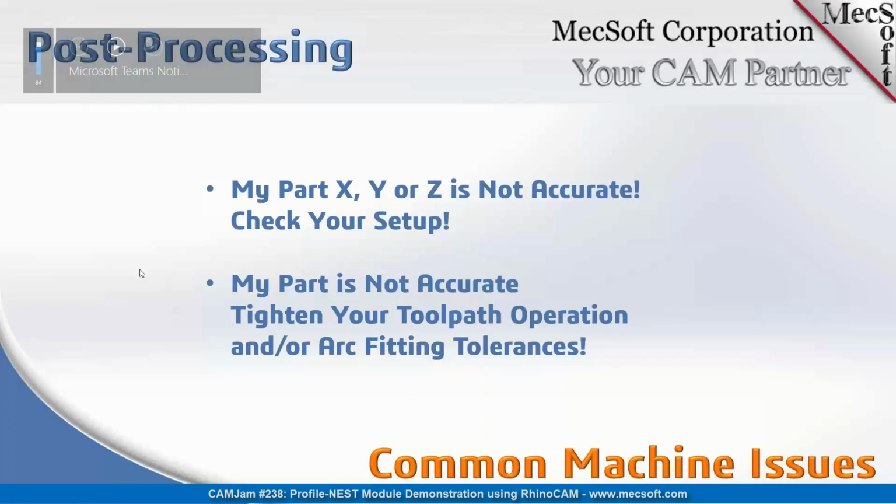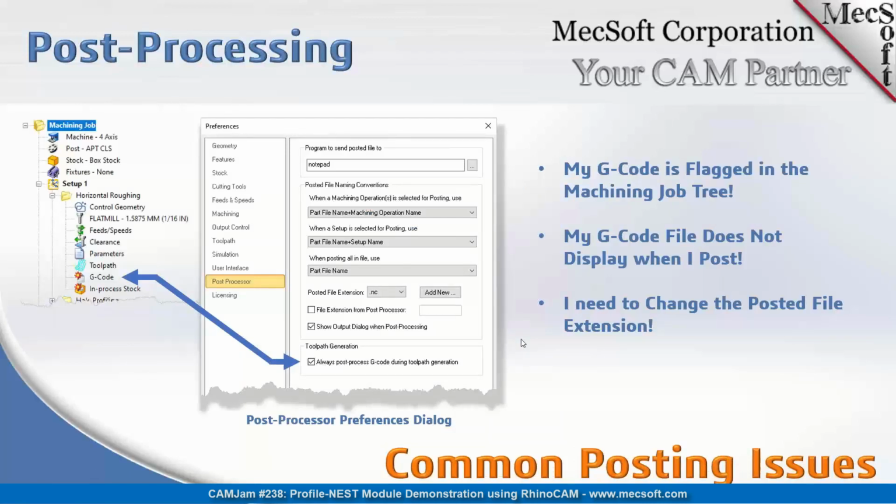Now here's a good question on upgrades, updates for service pack updates and things like that. Do your posts get overwritten? So yeah. Obviously if you edit any of the posts in our install path, do not save it as the same name, because those files are subject to be overwritten. If you use a unique name, correct me if I'm wrong, Joe, but I don't believe the uniquely named post will be overwritten when you do a service pack. I believe that directory, the entire directory will be overwritten.